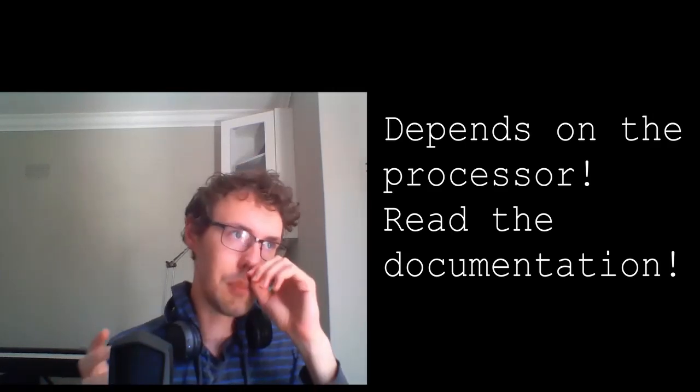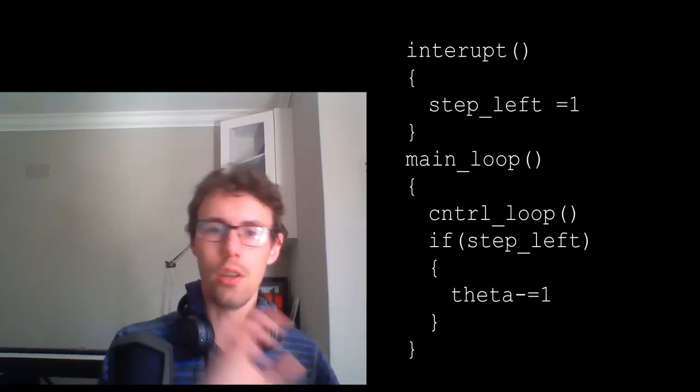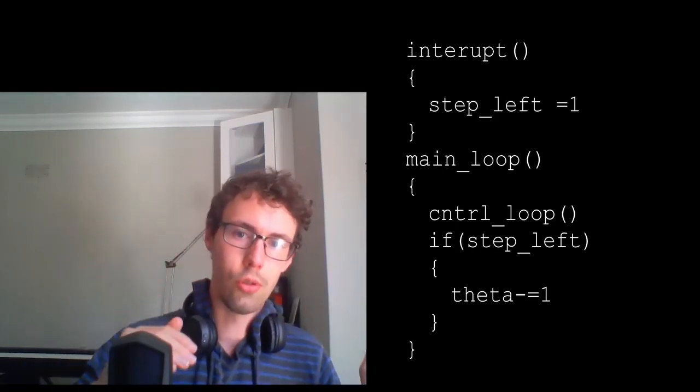So if you're going to code it, don't code the interrupt to do addition, just raise a flag and then put the addition code in your normal control loop, so that you know you'll always run through the control process, then add whatever the encoder told you to add, and then you can do the loop. You want as little code as possible in your interrupt sequences so that you don't saturate the processor and don't get back to your control loop.